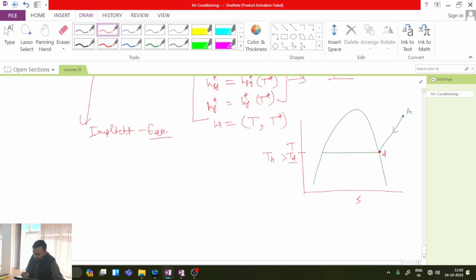Second thing, I said that if I have water and I adiabatically allow the water to evaporate, it means the enthalpy, or energy, of the air itself is used to evaporate water in order to provide the latent heat of vaporization.